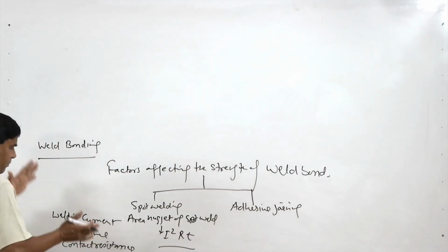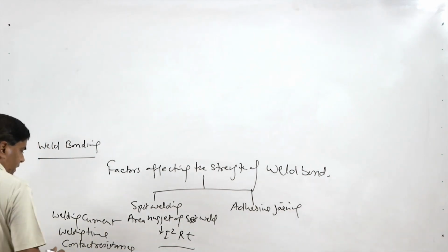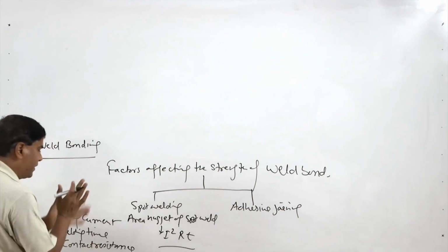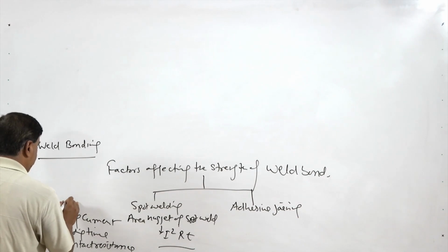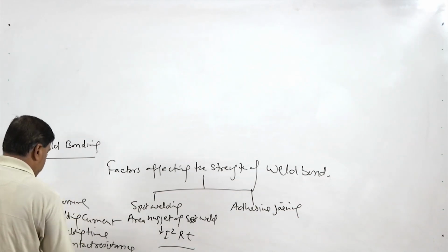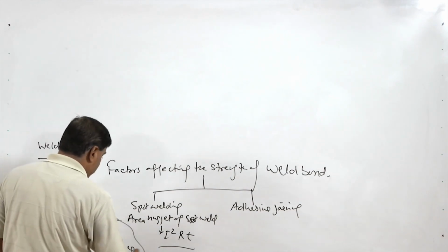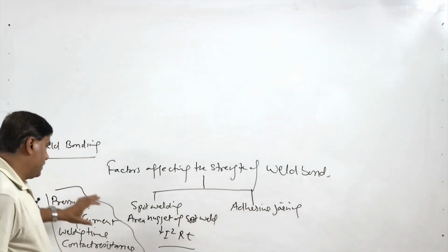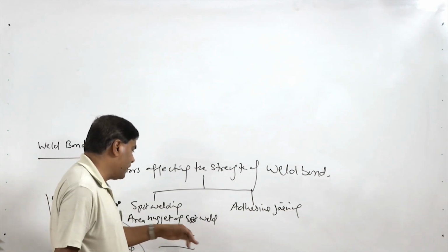From the process point of view, both the faying surfaces are kept under pressure, so that arcing is avoided and the consolidation can take place under pressure. So, the fourth factor is pressure. All these factors affect the heat generation by way of this I square RT.